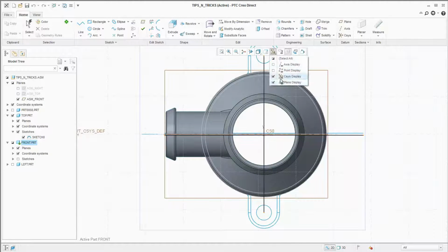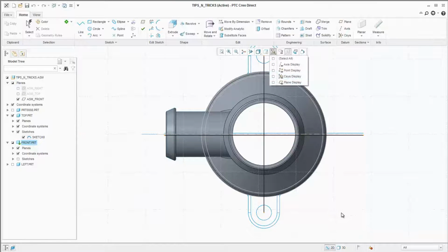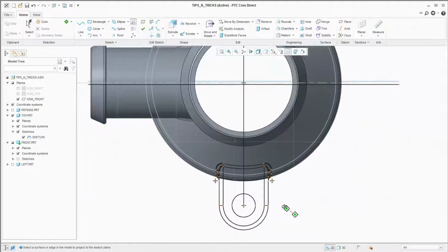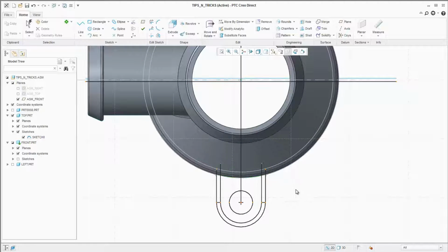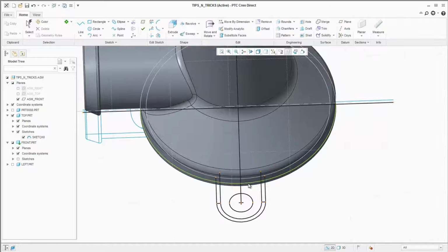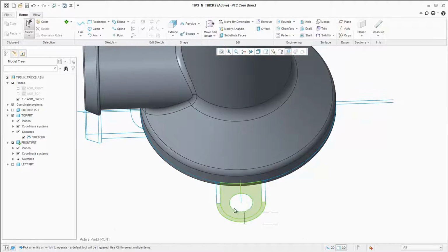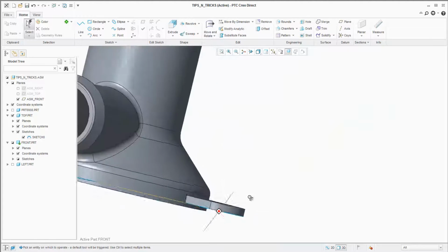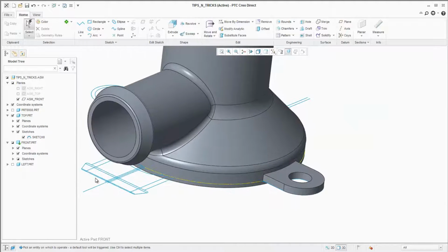In Creo Direct 3.0, sketches used for 3D geometry creation have to be inside the active part. That's why we use projection again to bring a meaningful subset of the top view geometry into a new sketch. Here I'm doing a quick cleanup and then ensure I have the outer edge projected and included in my sketch to get a closed contour. Selecting the sketch regions with box select from right to left helps to quickly include all of the regions being touched by the box. Deselect the hole and pull up the 3D geometry.